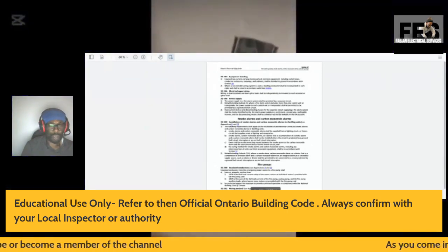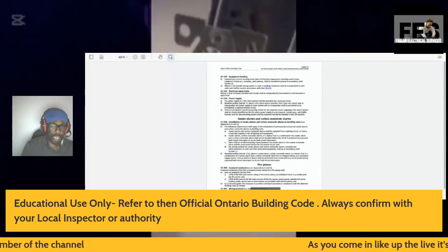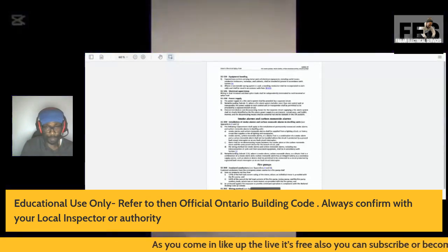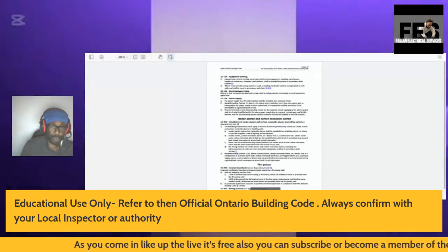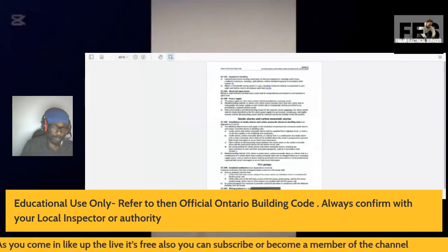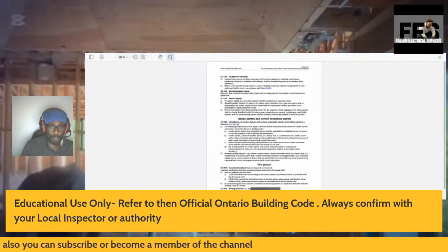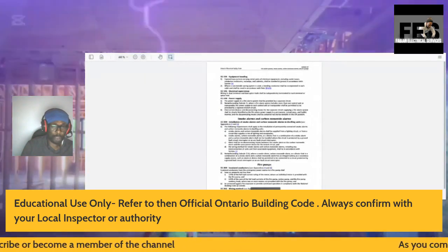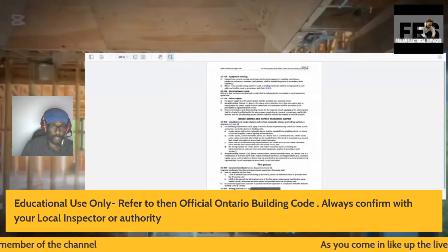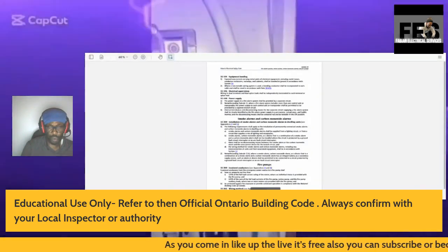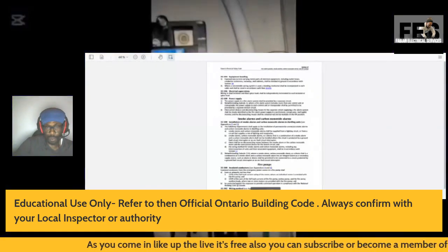If your battery is working, it will signal. Also, make sure that your smoke alarm, smoke detector is not expired. Max 7 years for the normal smoke detectors and 10 years for the other kind, the strobe-like smoke detectors.